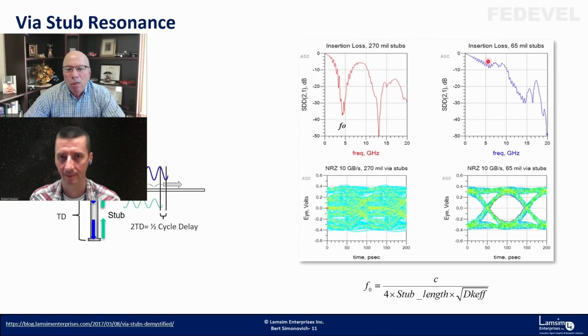So even though you have a channel loss showing there, the SerDes, the silicon, has equalizers to open the eye up more. So loss is important, but the silicon these days can take that into account.